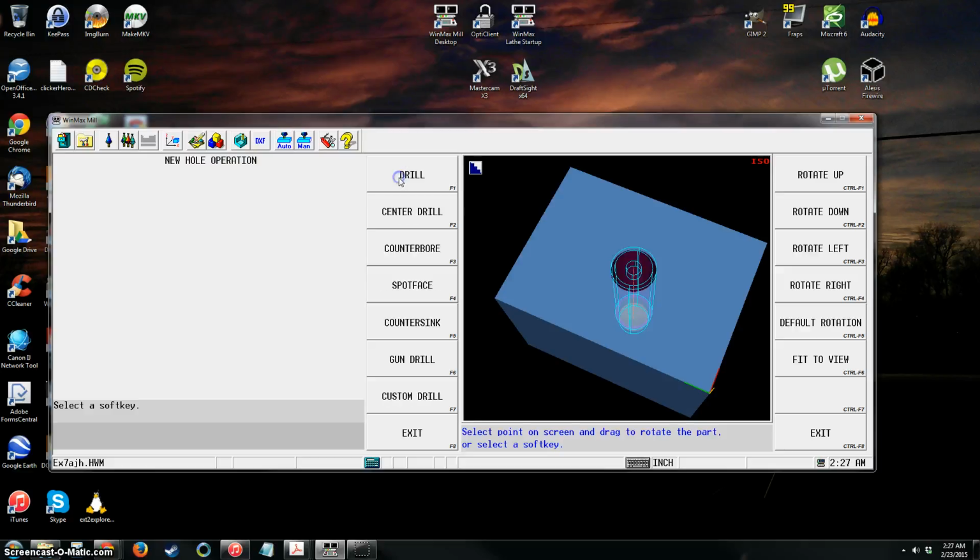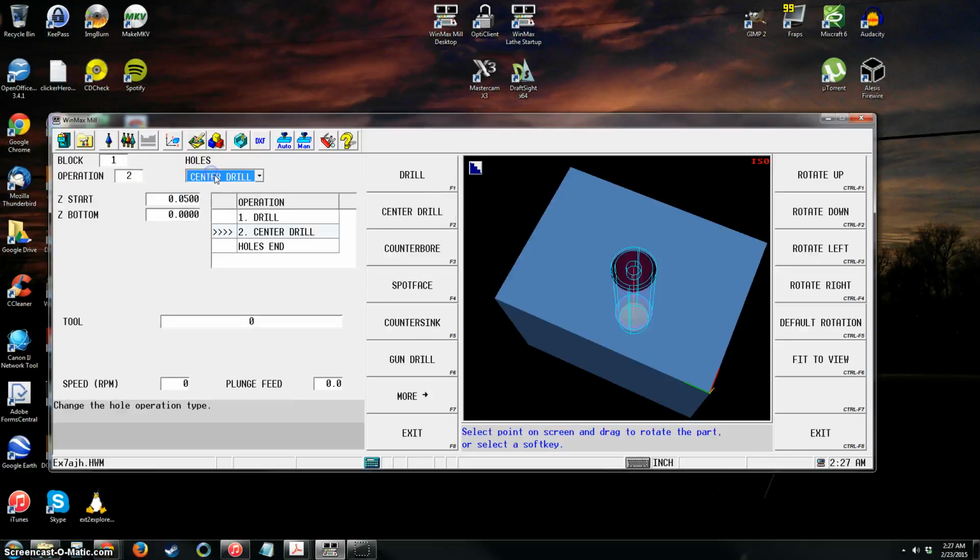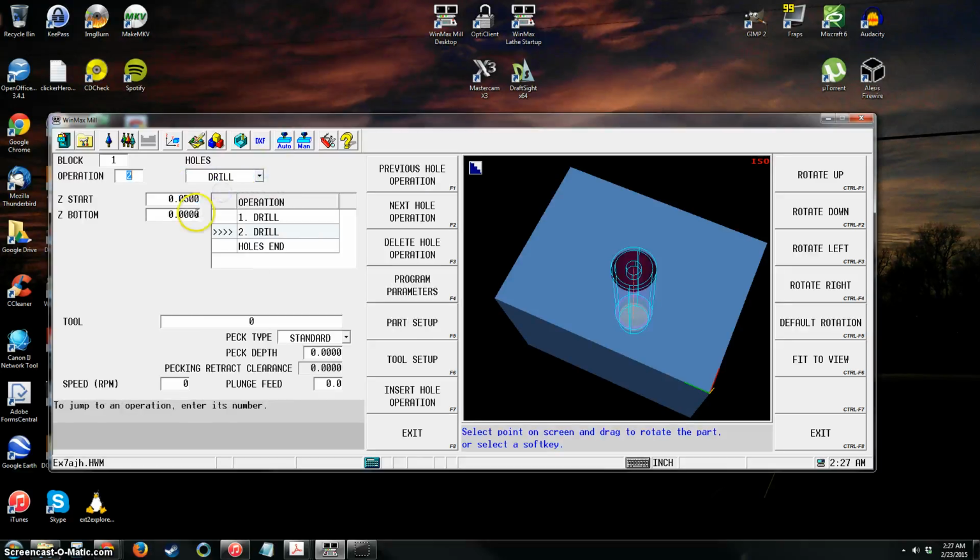And now we're going to do our actual drill block for our 3/8 drill. So our part is 0.25, but if we go that deep, it's not going to break all the way through. So we need to consider the tip size of our actual drill. When drills have angles like that, they're going to be offset from where you're actually going to be finishing your depth.